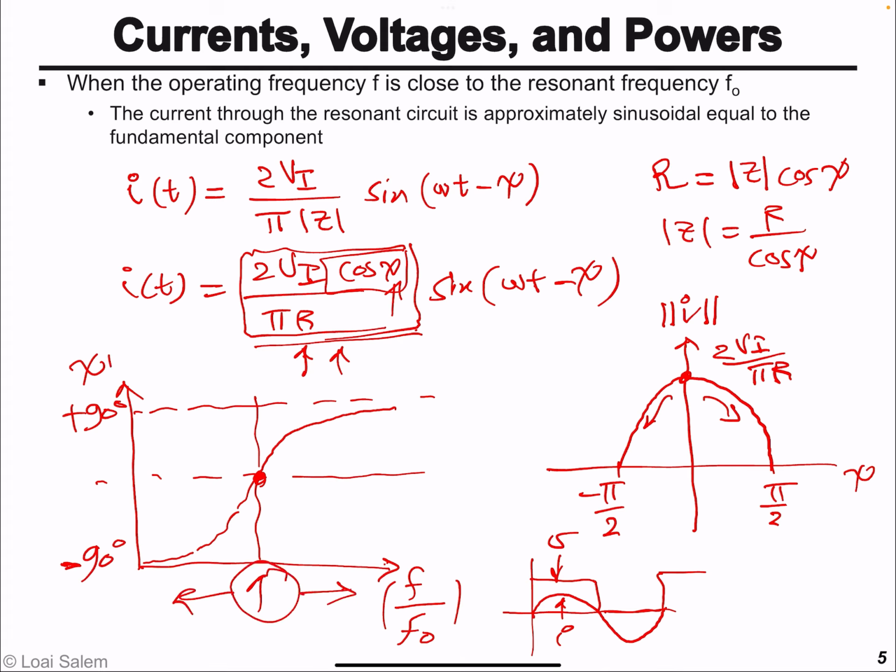It's going to introduce a phase psi, which lowers the current by a fraction via the cosine psi function. And so the amplitude of the current in the resonant circuit will decrease, and the peak value of the current in the resonant circuit happens when the switching frequency or operating frequency of the half bridge switches matches the center frequency or the resonant frequency of the RLC circuit.